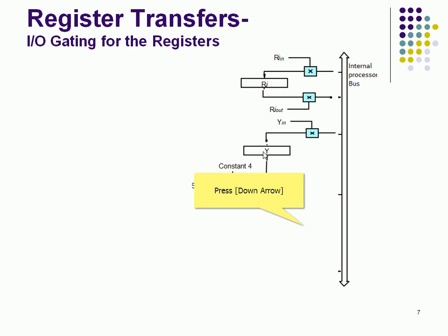We have seen this in the previous discussion. The ALU has a multiplexer. The multiplexer will have two inputs, one called constant 4 and the other Y, right? There is a select input, which will select either constant 4 or Y. Any one will come out, enter into the mux, and from the mux it will go to the ALU. So A may be either constant 4 or Y, the data will be there.